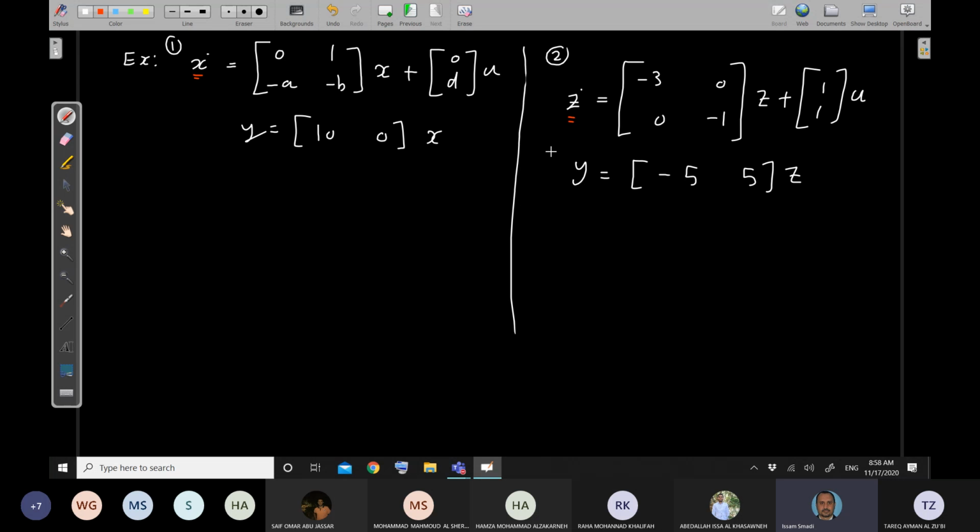And this is for sure to respect the math and the physics, because if this one was current, for example, this maybe Z would be the current plus the voltage, correct? So I cannot say that X1 is equal to Z1. If this is correct, then this one and this one must be identical. Simply here, I'm changing the state variable, and as a result of changing the state variable, the description of the system is differing, although I'm describing the same system. So who can help me to find the transfer function here?